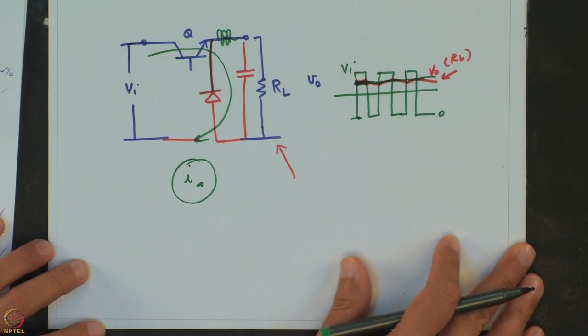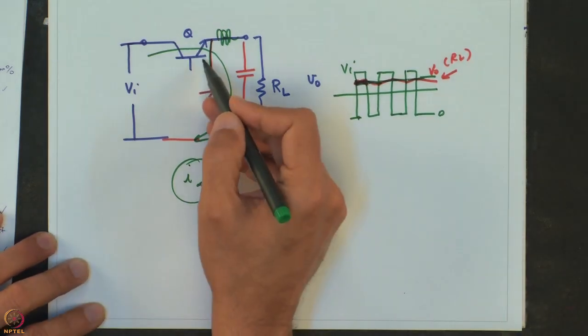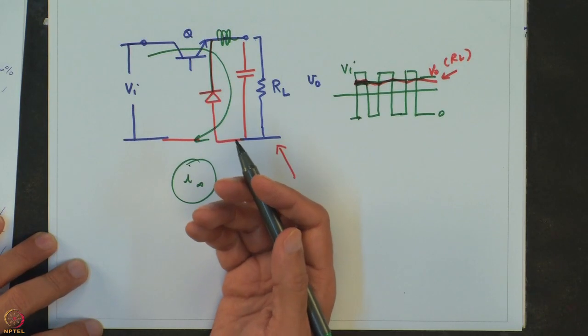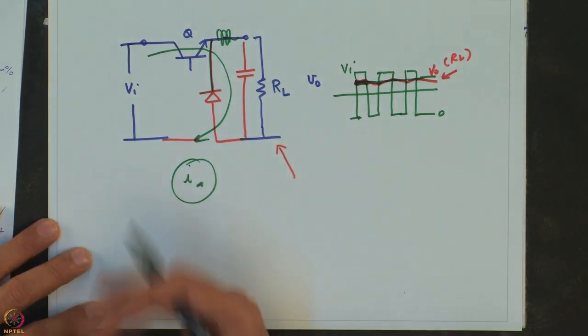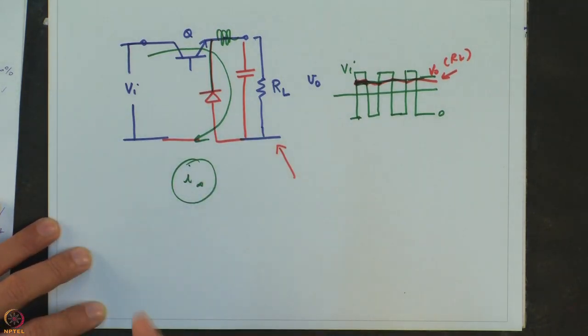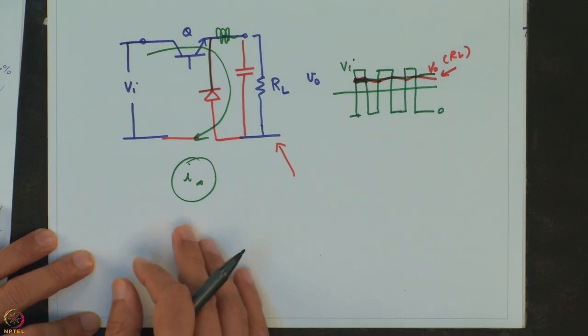It is a highly non-linear system, because your device is now not operated in a linear region, but is actually used as a switch going from on state to off state. So, switch mode power supplies are non-linear supplies. Now, if you look at the typical operation of this switch, the switch when it is conducting,